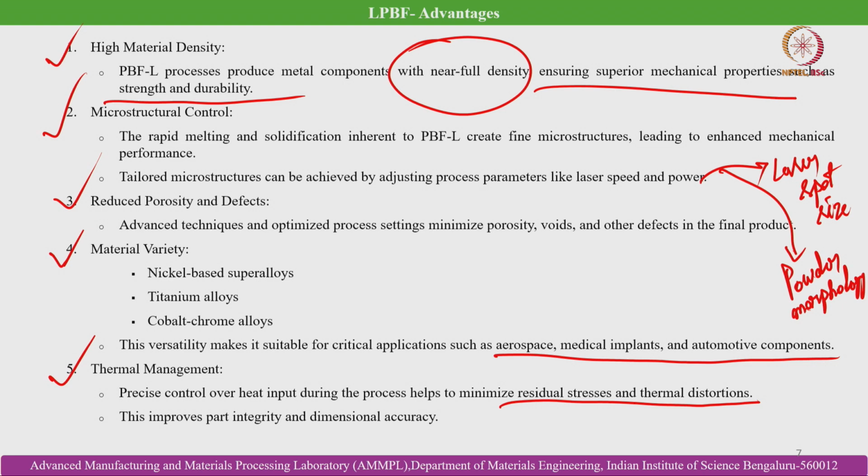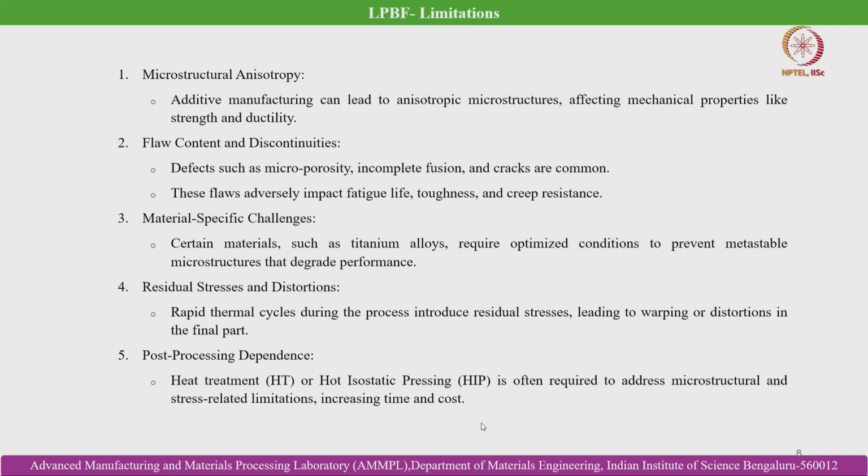because of the rapid solidification involved in this case. But precise control of the process parameters like heat input and scan speed of the laser can be tailored to minimize the residual stress and thermal distortions of the components after solidification, and this improves part integrity and dimensional accuracy. Okay. And then microstructural anisotropy. So, that is one of the key LPBF limitations.